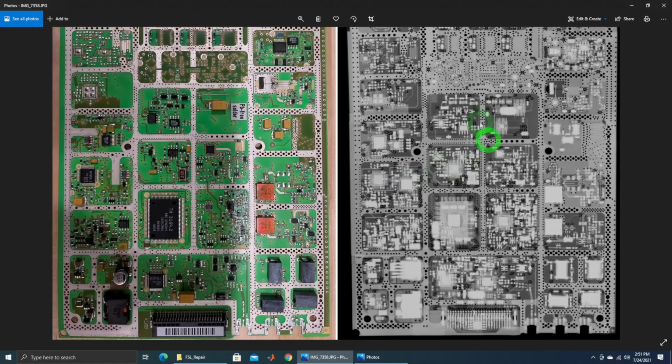And yeah, we could again go through every little bit of this, but I think for now we have enough information to at least begin studying this LO section. Make sure we do have our 10 megahertz, make sure we do have our VCO actually working, and we do have power supplies and signals coming into the phase frequency detector. These are the places that are worth paying attention to. So let's go and reassemble this, and then we can make measurements live on the instrument.